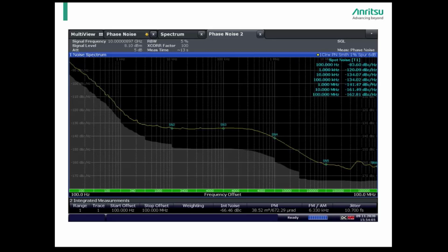It is clear that rubidium delivers an unprecedented level of performance from the live demonstration that we just showed. But how does that compare in the arena of various signal generators on the market currently? To make this comparison, we will use an actual screen capture of rubidium's performance. I will now juxtapose on this plot what will be known as the industry standard until now for standard phase noise. This phase noise is roughly around -120 dBc per hertz.